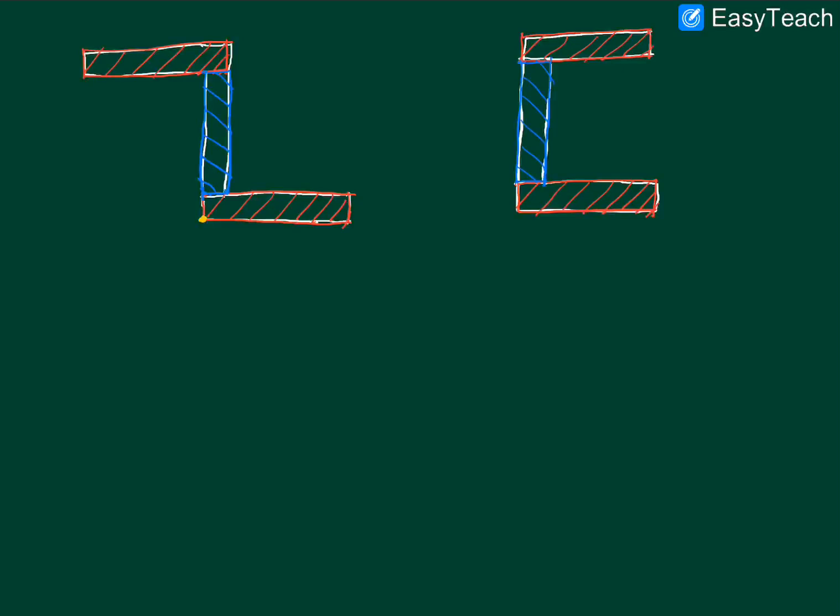Again, we can start off by imagining that our starting origin is here, and then we can find the centroid of this whole cross section. After setting up our centroidal axis, we can proceed to find the IZ, the IY, and the IYZ. And finally, we can have a very common engineering cross section, widely used, which is the famous I section.